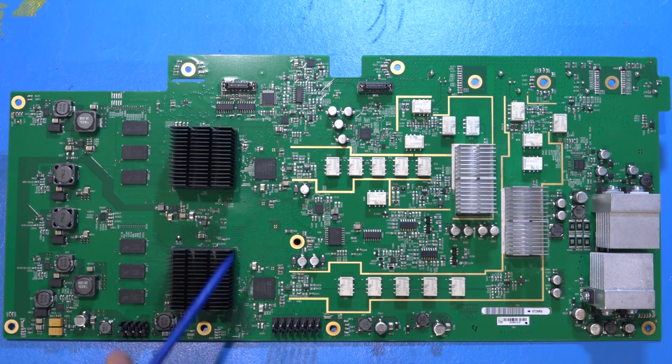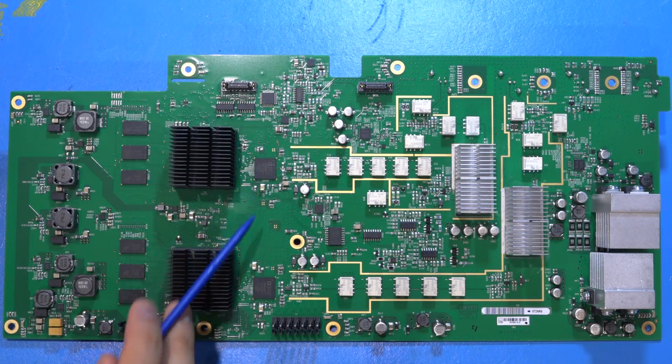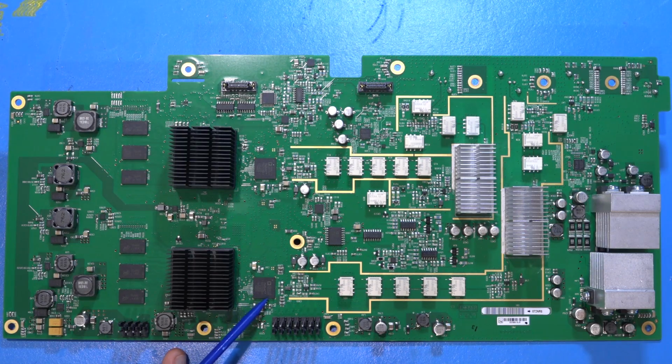And the reason this is very convenient is because if you're building, let's say, some kind of a communication device in the ISM band, then you would only need one SoC to do everything. You don't need to do mixers and so on. Everything is done in the digital domain. But it's not how they are used here. They're used in their baseband mode, which can produce signals from DC all the way to 1.25 gigahertz. Again, they're not used all the way to those frequencies. They back off the output frequency in order to be able to maintain a 250 megahertz bandwidth.